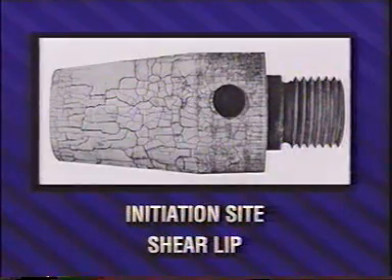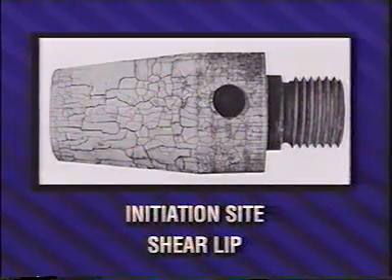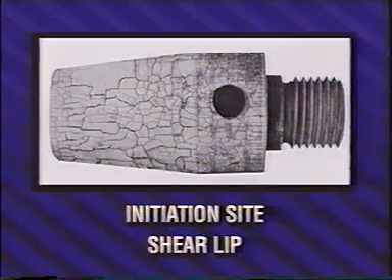Most thermal fatigue fractures are low cycle, high strain. The fracture surfaces are rough and faceted at or near the initiation sites. They are more fibrous with shear lips at 45-degree angles in the final fracture area.